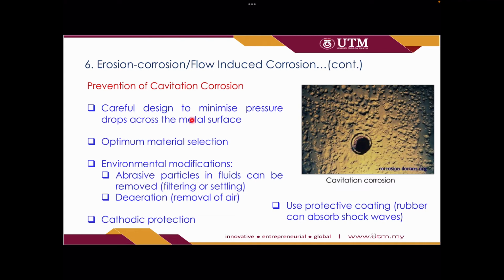We can carefully design or minimize pressure drop across the metal surface. We can optimize the material selection, high wear resistant materials, okay, environmental modification. Make sure that if there are liquids or gases involved in your system, any system like a boiler or any plant, you filter all the solid particles, okay, maybe you can eliminate poisonous gases such as chloride and everything.